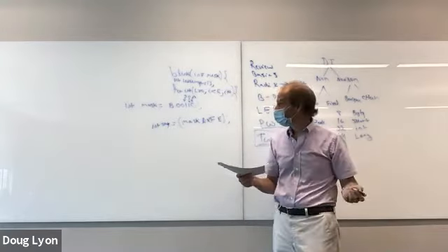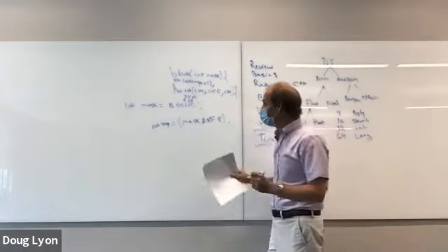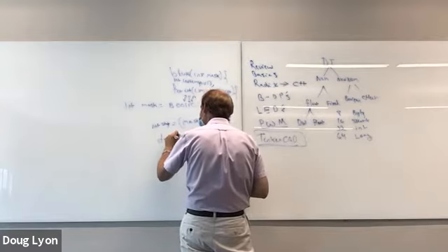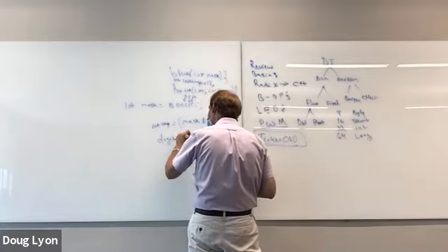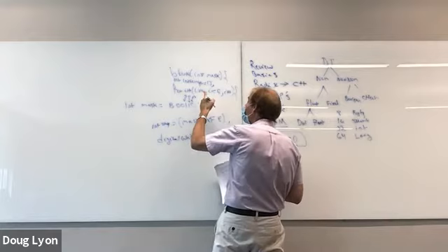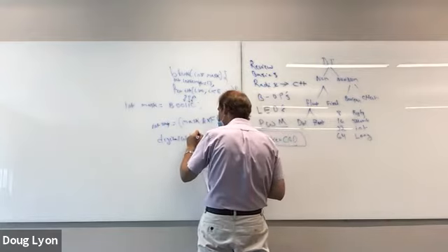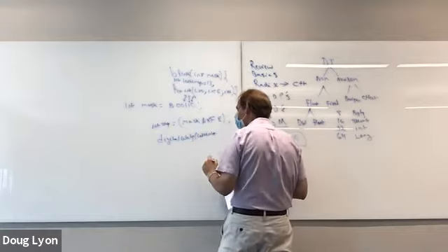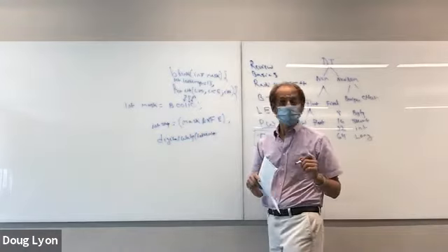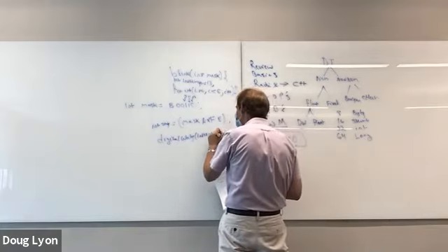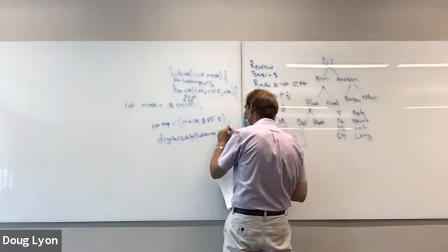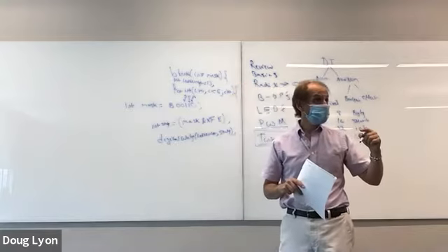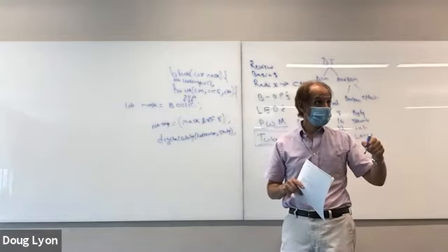So now all I have to do is get the actual LED number and do a digital write for LED number, and I'll write the state. LED numbers are decreasing by 2 each time, so I go 12, that's going to be a ground.